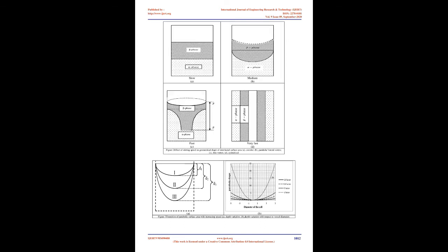Danckwerts and M.M. Sharma proposed a mechanism for finding the reaction regime, classifying reactions into four types as regime 1, 2, 3 and 4, based on mass transfer theories and other hydrodynamic parameters. Hatta proposed a dimensionless number, the Hatta number, to show whether the reaction occurring in the liquid-gas or liquid-liquid phase is slow or fast. Based on the Hatta number, Doraiswamy et al. have classified the limiting criteria proposed for the identification of reaction regime into two zones as shown in Table 1. If the Hatta number is greater than 1, Ha>1, the reaction is fast and takes place in the film, the surface area is the controlling factor and it falls under regime 3 or 4. If the value of the Hatta number is less than 1, Ha<1, the reaction is slow and does not take place in the film, the bulk phase is the controlling factor and the reaction falls under regime 1 or 2.